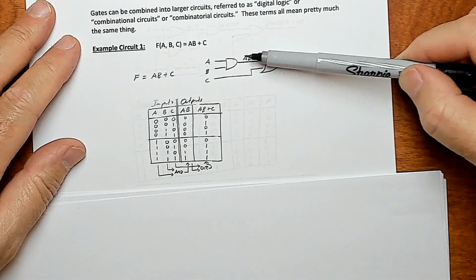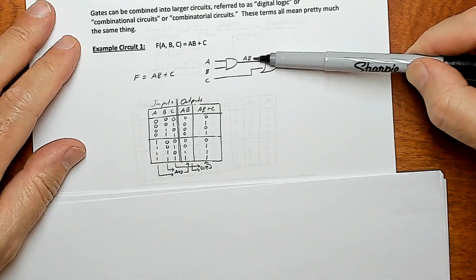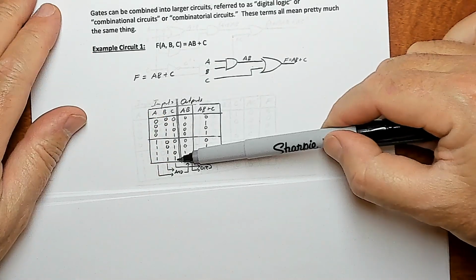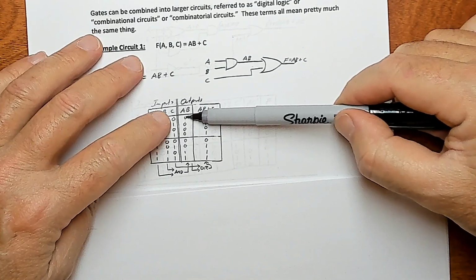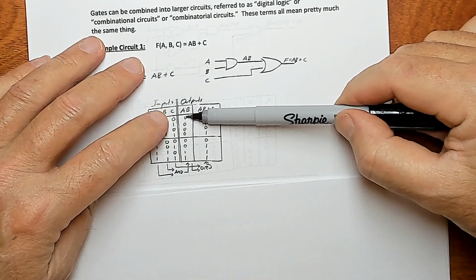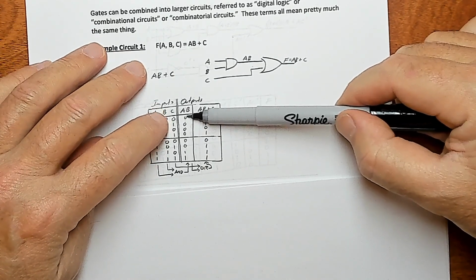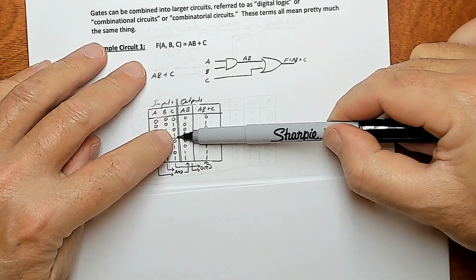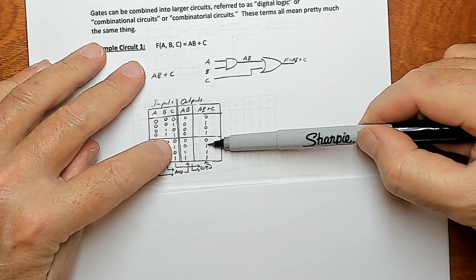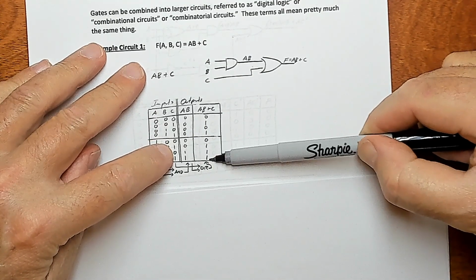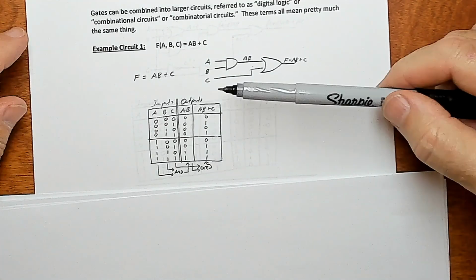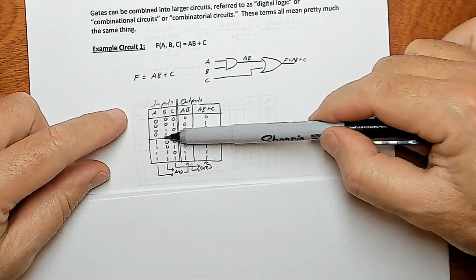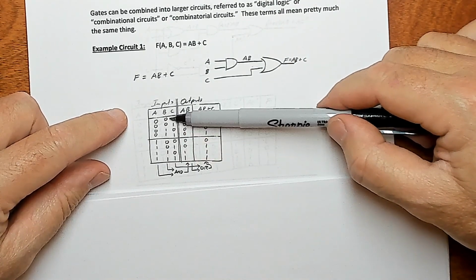Then to do this OR, you take ab and combine that with c. So we're looking at these two columns, the ab column and the c column, and in this case, we're looking for at least one 1, one or more 1s, right? Here's a 1 on c, so we got a 1 there. There's a 1 there, so we got a 1 here and here, so we got 1s there. So that's the final output, f. We've basically defined the output for any possible 3-bit input of this function.